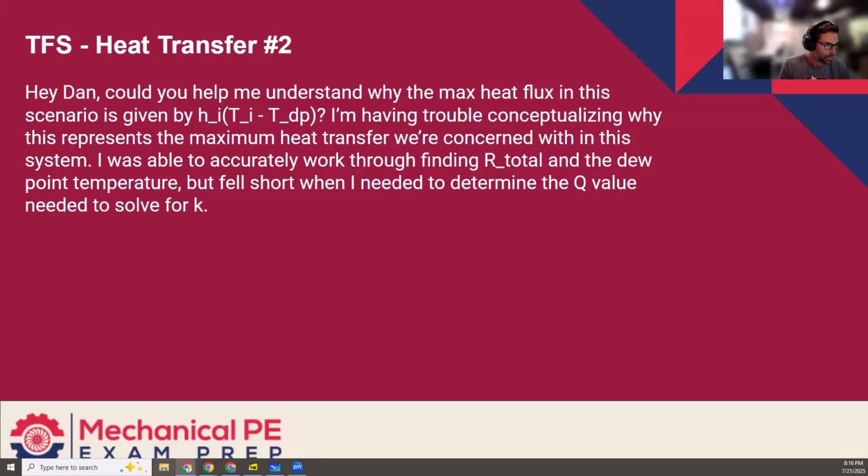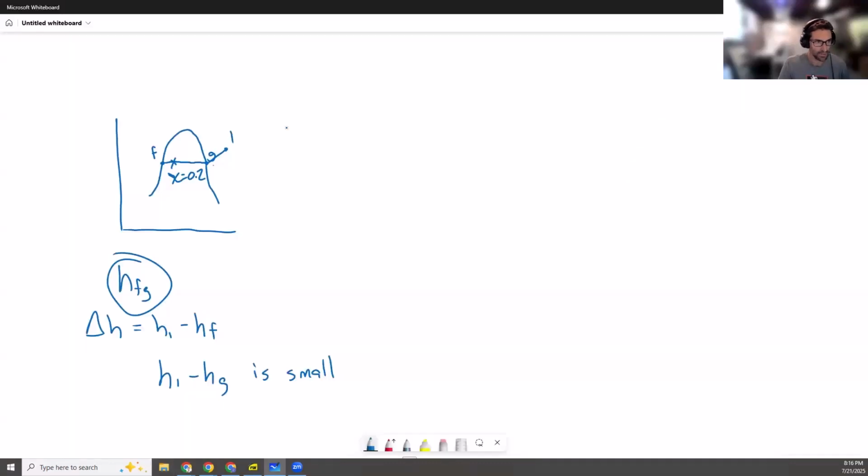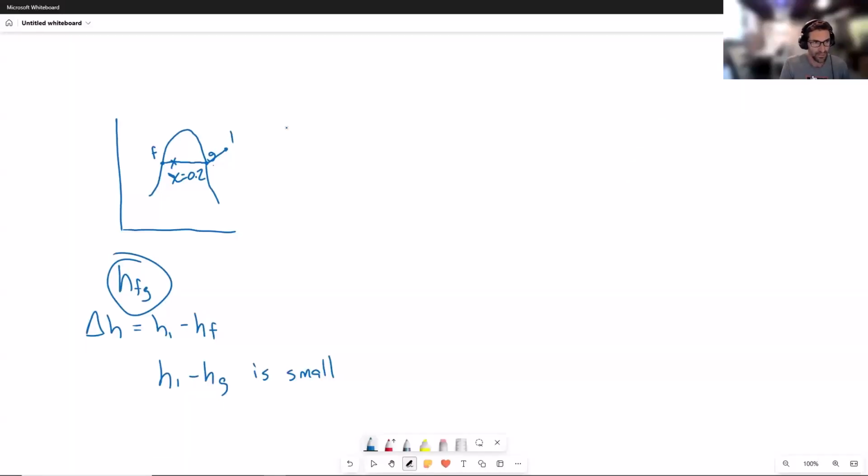So that first layer of the composite wall, I'm not going to redraw the whole composite wall, but just think about that first layer. We have an internal temperature of 70 degrees dry bulb, and a relative humidity of 60% RH. So that's a fully defined state, and we can find the dew point associated with it. That's going to be 55.6. I'll put dP for dew point.